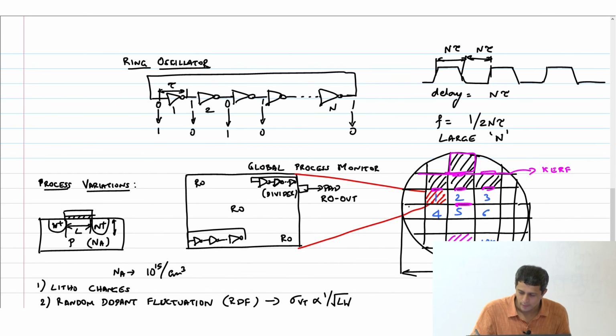So you make measurements here, make sure everything is fine, and then you cut it. The ring oscillator doesn't matter after that, because once you have made the measurement, you can as well clear it. So it's interesting that a simple circuit with just inverters actually has so many uses.